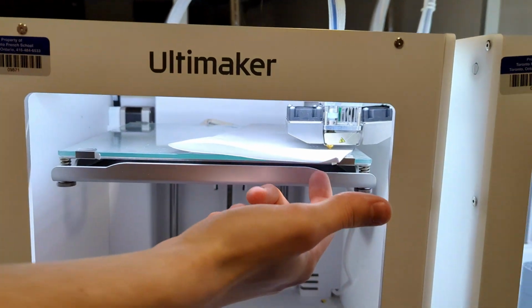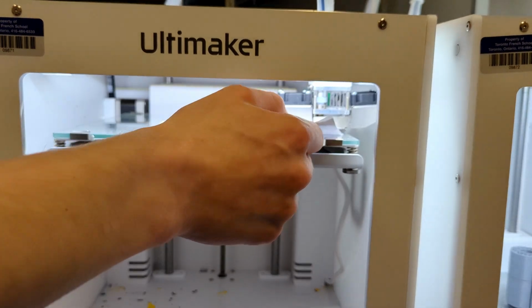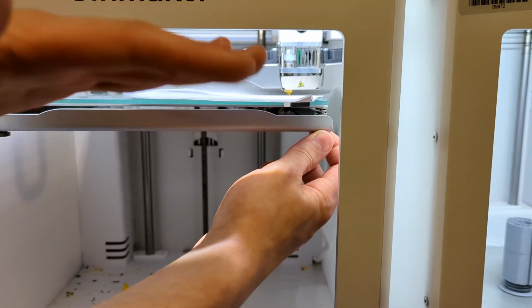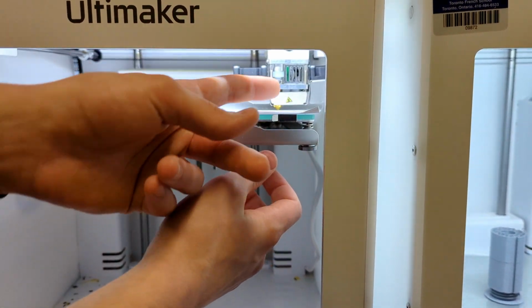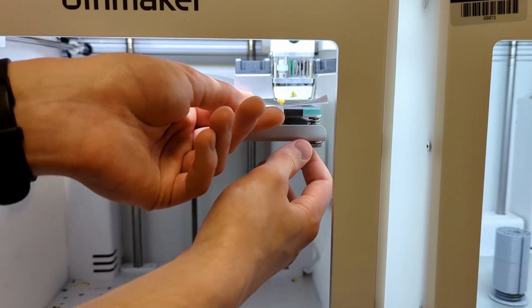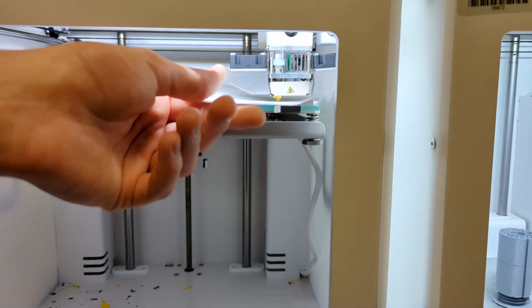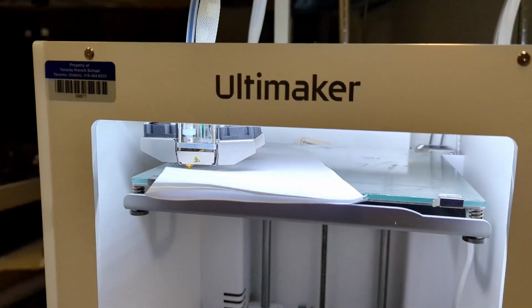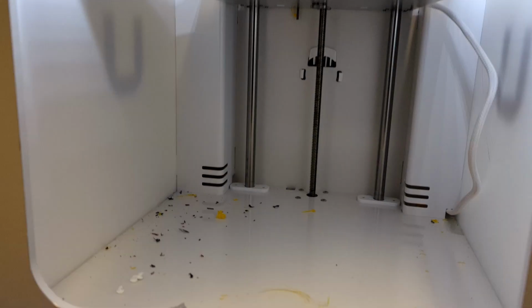So now it'll bring us to this front corner. See, it goes over each one of these screws, basically. This one is already pretty good, actually. So you tighten the screw to bring the bed down, so more space. Now if we loosen the screw, we're making the space tighter here, and it's a little bit too much resistance. So we're gonna just leave that how it was. Done adjusting. Same thing here. It's already good.